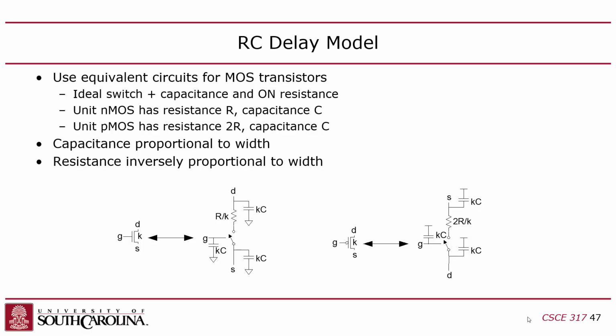And the idea is that if, let's say I have an NMOS transistor, the gate is connected to a capacitor to ground, right? Why? Well, because the substrate is grounded, right? The channel, right? Likewise, on a PMOS, it's the same thing, but there are capacitors to VDD on the gate, right? You guys with me? So that's the gate capacitance.